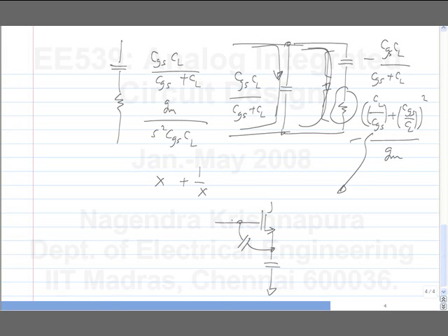You want some source of incremental energy to compensate the loss of the tank circuit you have. So you should maximize the effect of negative resistance. So you make this ratio close to 1, and that has implications on how easily it oscillates. If you make one of them very small compared to the other, it will probably not oscillate, or you will need a very large GM to make it oscillate. Note that this also depends on the value of GM.